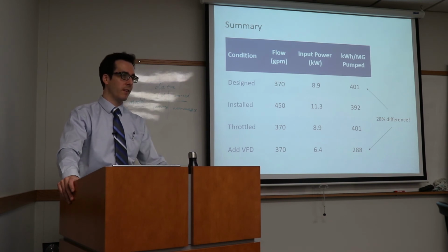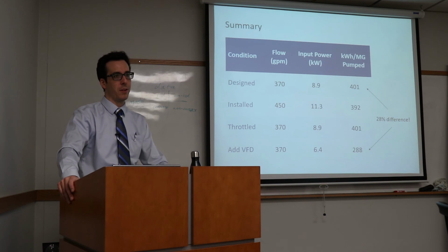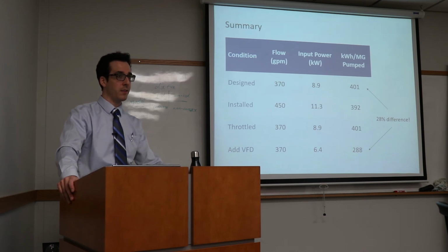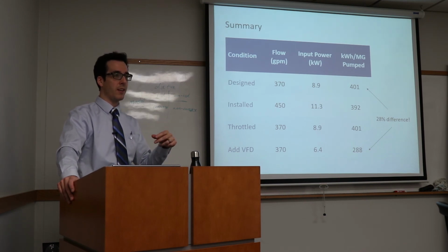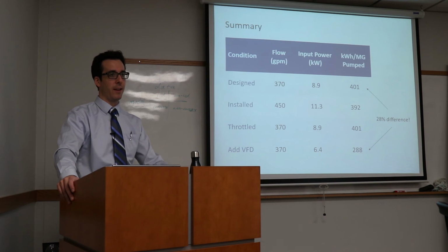But to your question, we don't see pumps in series. You see them in parallel. If they need to turn on a second one and get a little bit more flow, they do. As you probably know, with pumps in series, you add head to the same flow. With pumps in parallel, you add flow to the same head.